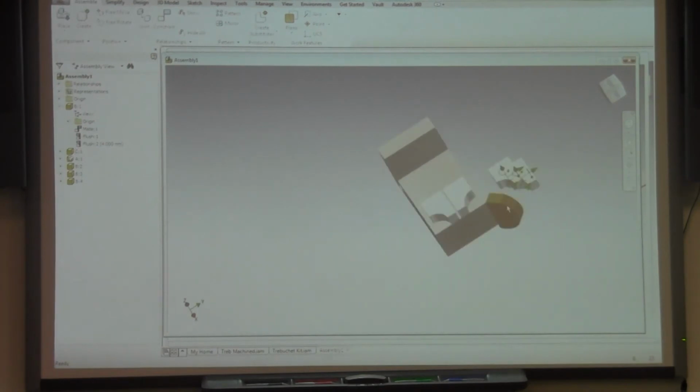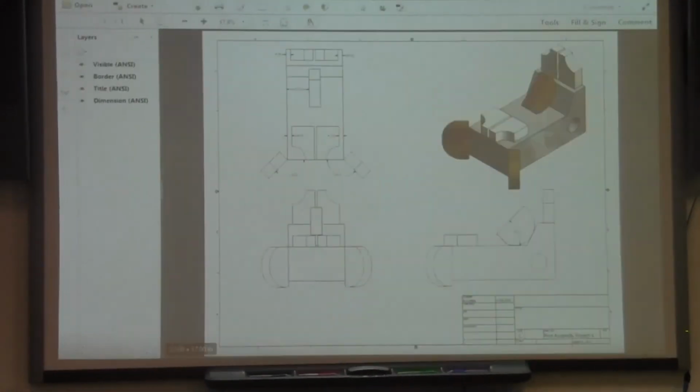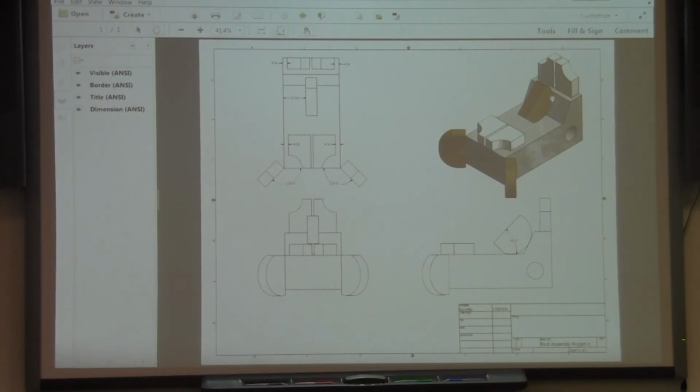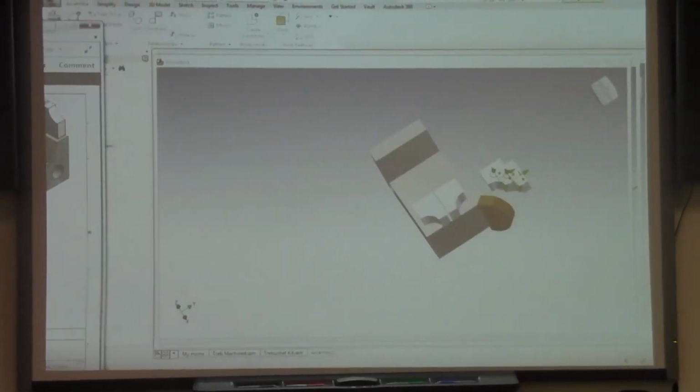Now, in your model, you'll stick another one over here on this side, per this drawing right here. What I want to concentrate on right now is this shape right here. I'll need to go copy one of these, and so I can throw it on here. But you'll see that this shape is tangent to this back angle piece, and it is tangent to that flat piece right there. And additionally, it's set in there with a 45-degree angle. That's what we're working on next.